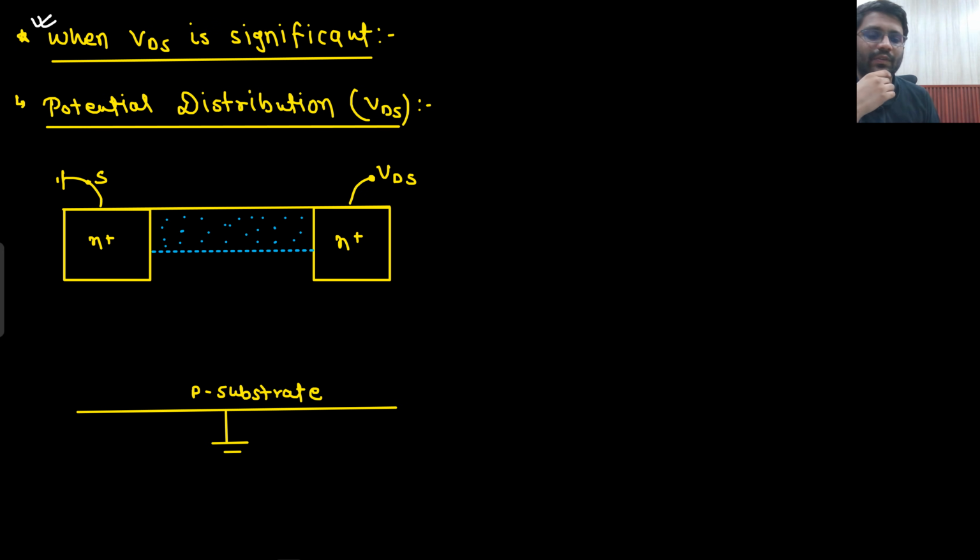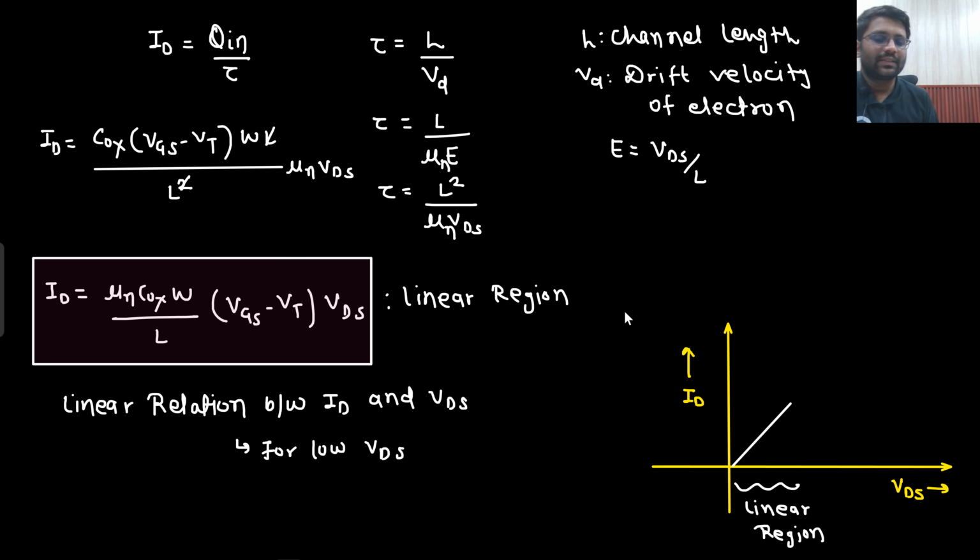Yeah, welcome back guys. So, we were studying about MOSFETs. We have seen this characteristics for low VDS value. And when we are drawing the characteristics, we are keeping VGS constant, right? This has been drawn for a particular VGS. Someone would be saying that, sir, your ID is depending on VGS as well, it is depending on VDS as well. You are drawing ID versus VDS for fixed VGS.